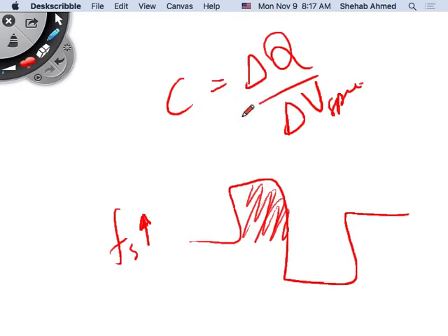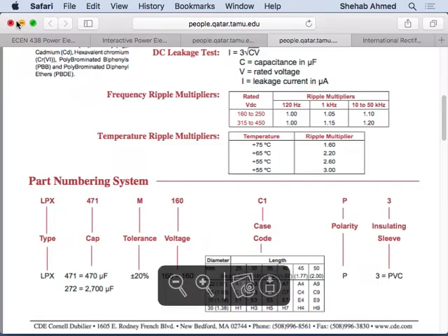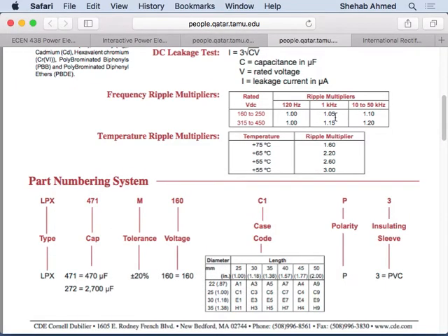So if I maintain the same capacitance, I should be able to push in current with higher ripple into this capacitance. So higher ripple current. And that's what they have here. They multiply the ripple current by something higher. That doesn't help, it doesn't improve too much at the end of the day, because you're going to be limited by the average power loss in the resistor ESR. It's inside the capacitor, so it's going to heat the capacitor anyway.